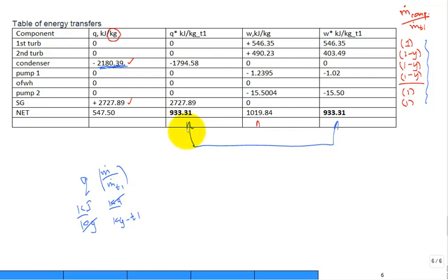I know it's a long way setting it up, but what's the thermal efficiency for this cycle? So our thermal efficiency for the cycle, I just put a TH there for thermal, is how much work is out. So the W net divided by what? The Q in, and you only have one place for the Q to come in.